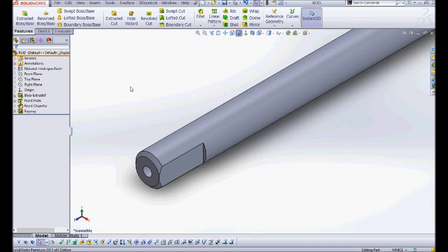What you're going to do is draw that vertical line and then try to trim it using the power trim. Be very, very careful because you're now armed with a machete. If you accidentally destroy geometry that you want to keep, use Control Z or undo. Question: are we concerned about the horizontal position of this line? We will be in a second; we'll be controlling that. But right now, I just want you to draw the vertical line and then try to trim out your geometry.